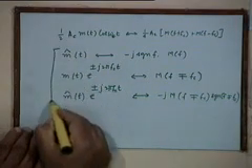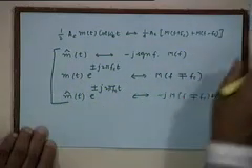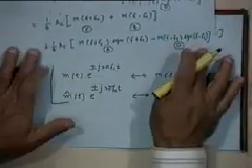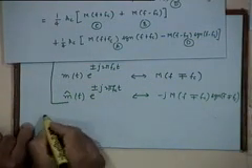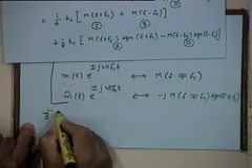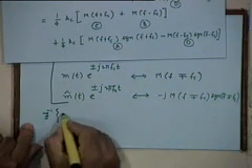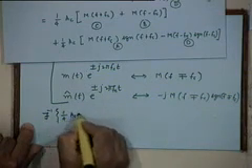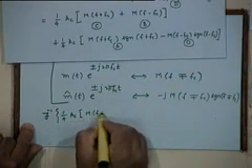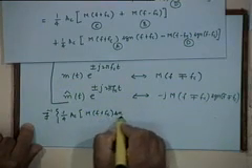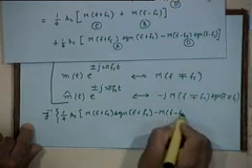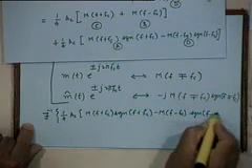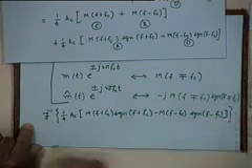So now, keeping these three basic results in mind, let's look at the inverse Fourier transform of the last two terms in this expression. What do they correspond to? So if I look at the inverse Fourier transform of the terms 1 by 4 AC into M of f plus fc into signum f plus fc, minus M of f minus fc signum f minus fc, which is the last two terms.